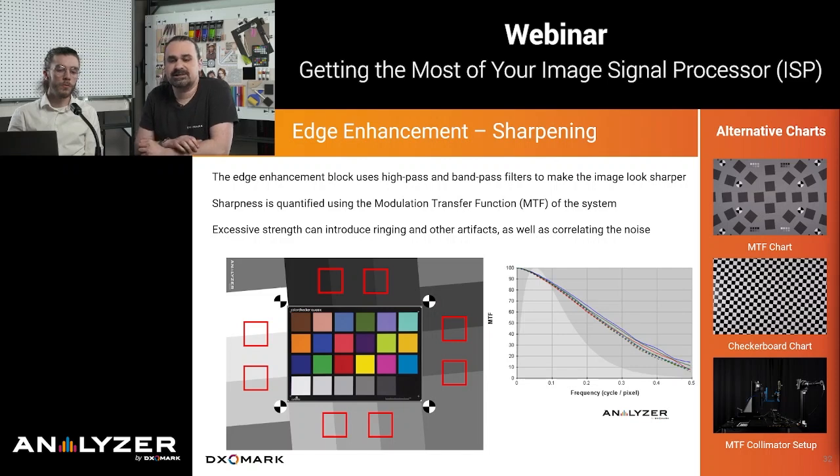Specifically, I want to weight it in a way that makes sense with my perceptual impression of sharpness. How do I do that? There is a notion called acutance, in which the MTF is weighted with something called the contrast sensitivity function, which is the lighter gray area that you see in the MTF graph. And that represents how sensitive the human eye is to that specific spatial frequency in certain viewing conditions that you have to choose for your analysis.